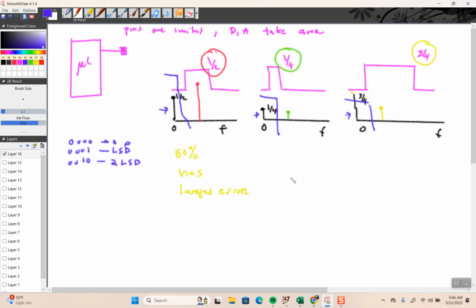And what kind of filter does that? A low pass, right? What is the best kind of filter? Most Butterworth, right? That means the damping coefficient is 0.707. Complex poles.